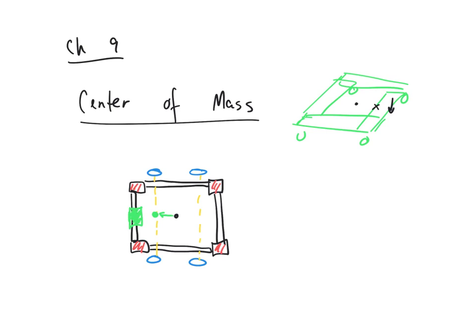What would be an example of something that has variable density? It would be like this, some part of a door. This is not isotropic at all. This material is different than this material, and there's a concentrated mass over here, and it's not over here. This is a different density, or this metal, which is different than glass. So this would not be a system in this case that is isotropic or the same throughout. On top of the fact that this is obviously a concentrated load right here, or a mass. But even the material properties are changing throughout the solid.